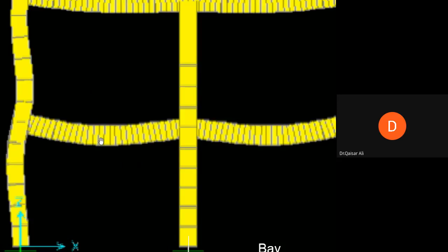So as we have explained in the previous lecture, if you have to reinforce this beam with steel bars, you will have to place steel bars at the bottom of the beam at the midspan, and at the top portion of the beam at the location where it crosses the column. Because if you look at the behavior of the beam when it is loaded, there is nothing below the beam between the two columns at the midspan.